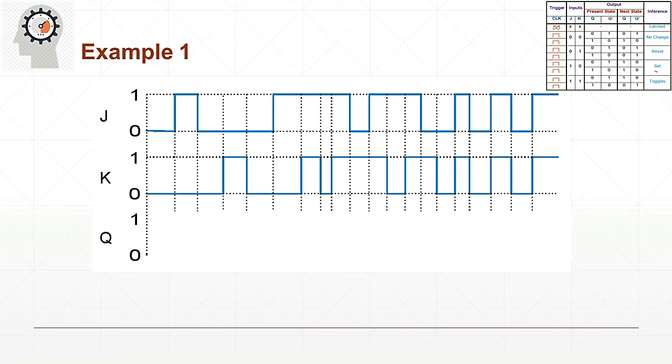Remember that the low line represents 0 and the high line represents 1. That's what's indicated in the given. After putting the value, by each column, get the value for J and K. Make sure that you memorize and become familiar with the truth table for the JK flip-flop.